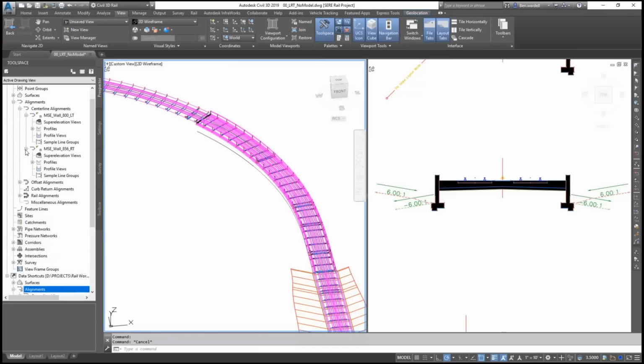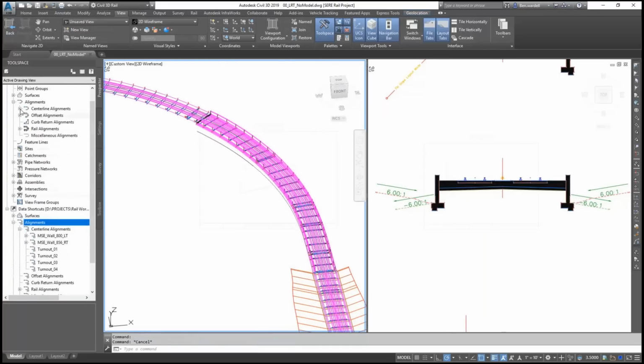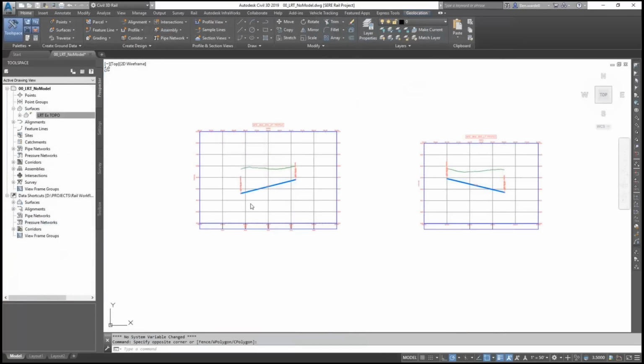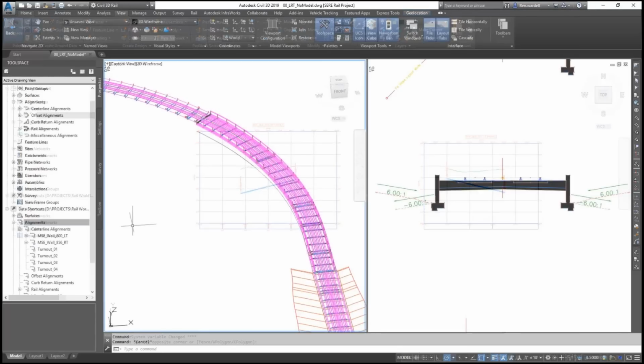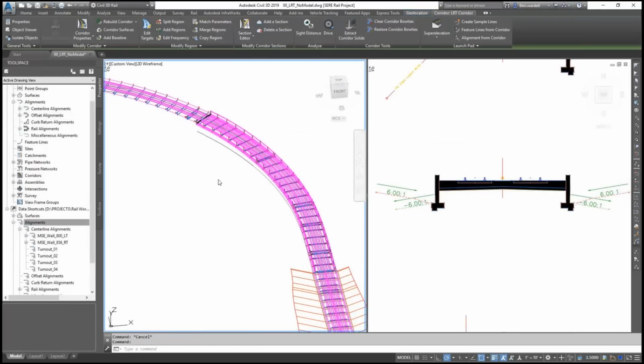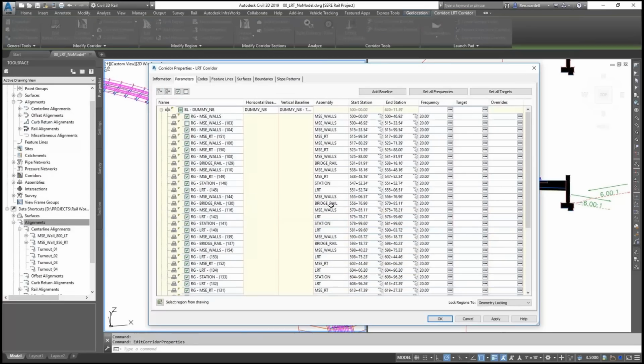We might have a wall height that we know we have to hit for something that's going on, and that's the case in this area. This is a whole area slated for development. We can look at this profile as well and see this is the proposed bottom of the wall there. And so we want our model to go down to that point and then cut out up to existing ground. And so in that area, that happens to be right there.